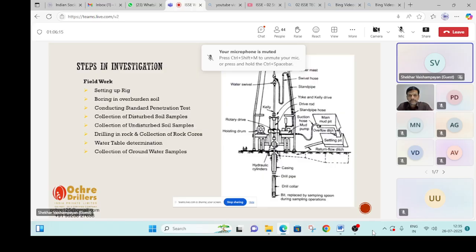We can call it jugaad in site language, and then we reconstructed the structure. Now it has come up today. Such a thing is also a structural hack, but it requires a lot of help from a structural engineer. It is not the work of a pure geotechnical engineer, because the analysis became very critical. Which piles are loaded, which are not loaded, and the piles which were discarded were cut well below the pile cutoff level, and they were not allowed to take any load at all. Such a thing we have physically executed. This did happen.